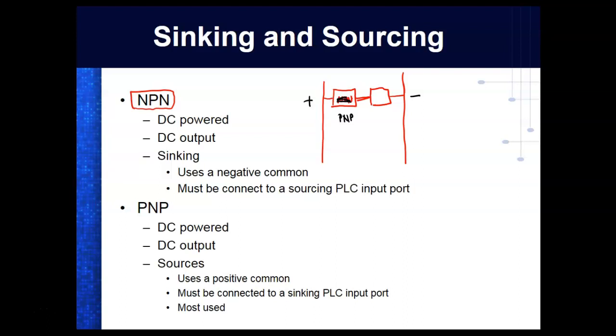And why? Well, say you need an optical sensor. This company makes both the PNP and the NPN, but you get the wrong one. You go, okay, I need a through-beam sensor. You go up there and say, oh, there's one up there, right? And you buy the wrong one and you hook it up, what's going to happen? It's not going to hurt the sensor. The sensor's just not going to work. Oh, they sent me a bad sensor. Let's order another one. You order the same one, put it in there, it don't work. Oh, the PLC's bad. Let's replace the PLC. Put it back in there, it don't work. Right? You understand? Because you're buying the wrong sensor.